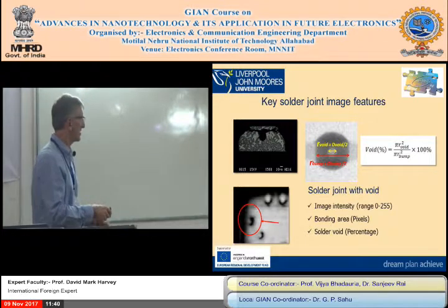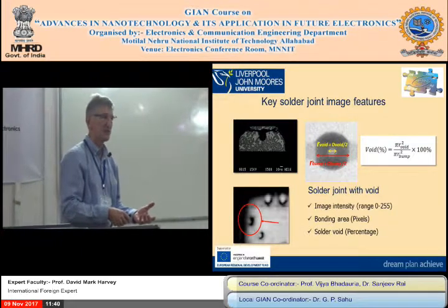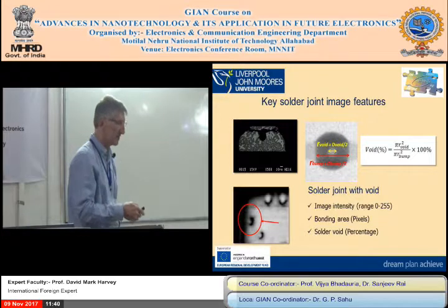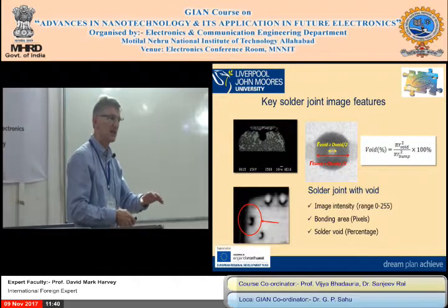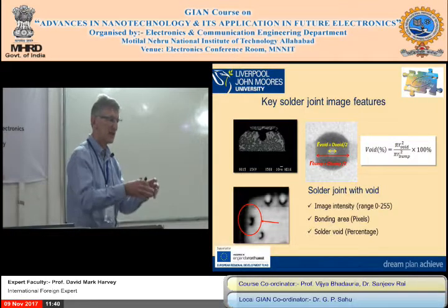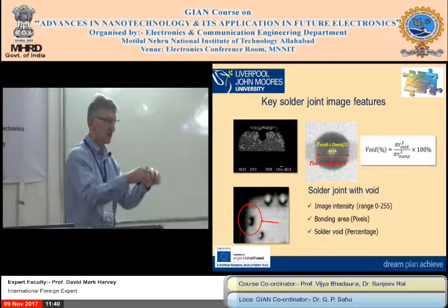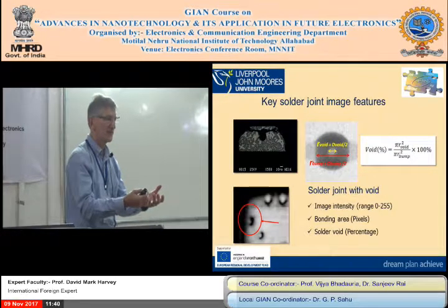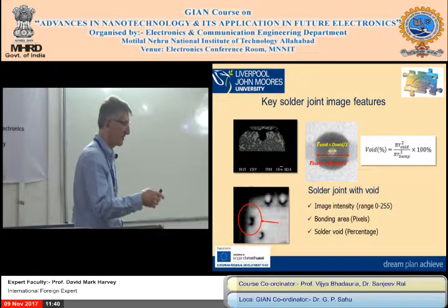But that's the big one, but you could get several smaller ones. You might get 5 or 6 voids. 1 or 2 is okay, because if you get too many... do you know what an Aero bar is? You get Aero chocolate bars here. It's like an Aero chocolate where you smash it. If you've got too many bubbles, it's got to have a weak point and it'll break more easily. 1 or 2, maybe okay.